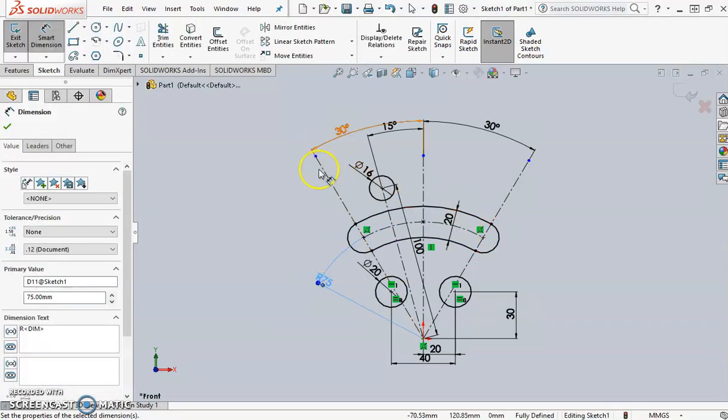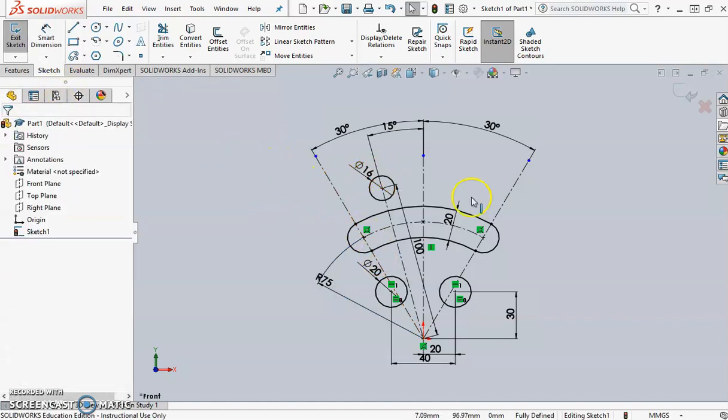So the nice thing with having these construction lines here, it gave us a start and stop spot. The slot also slides up and down it, and you can see all of the points are perfectly in line with those construction lines. So that whole inside is now done. Now the tough part, that's going to be the outside.